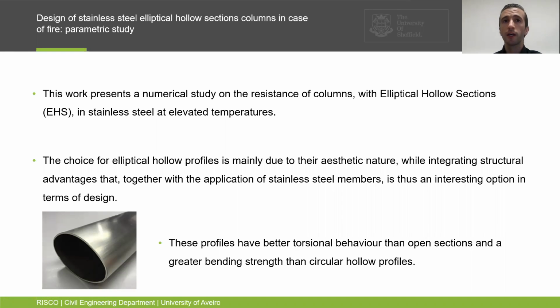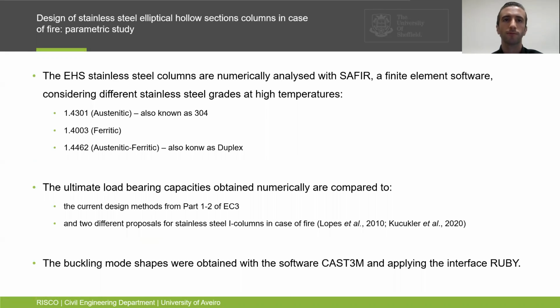This research is about the elliptical hollow section stainless steel columns at elevated temperatures. Elliptical hollow profiles present a nice aesthetic nature, have different structural advantages, and considering the stainless steel material, it seems to be an interesting option for design. Also, the elliptical hollow profiles have better torsional buckling behavior than open sections and a greater bending strength than circular hollow profiles.